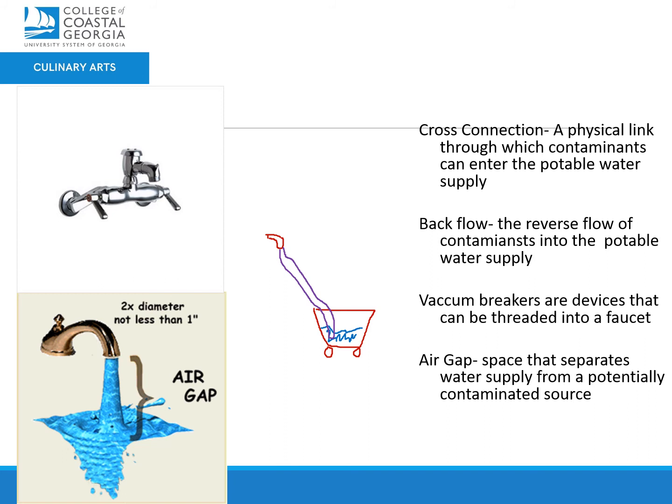Well, when you turn off the faucet up here, it can create a vacuum, just like siphoning something. And when you shut it off, it will actually draw water up the hose. So the water moves up the hose and into the faucet, and this faucet is connected to all the sinks in your facility.